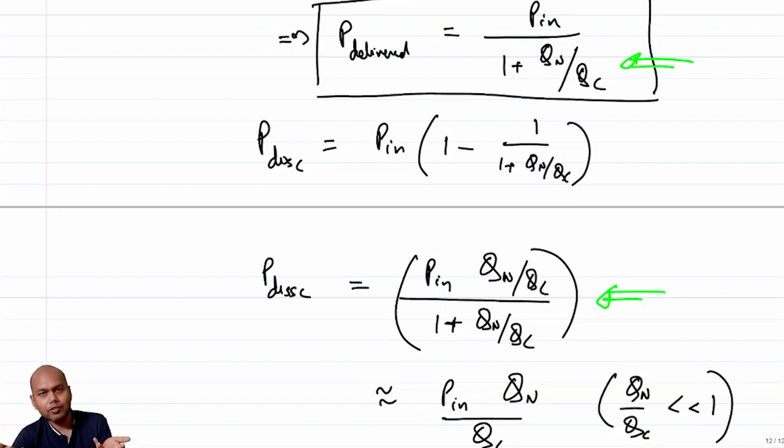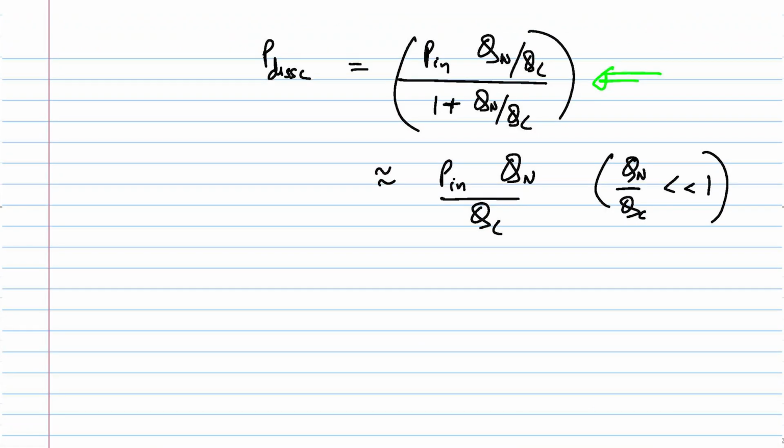Now, if you have a large Q of the network and you have losses in the components, then naturally this points to the fact that you are going to have a lot of losses. Granted, you might have some impedance transformation, but the amount of loss that you are going to have in the matching network in the process of getting that impedance transformation will make the matching network essentially useless, right? So in the next lecture we'll talk about a framework briefly, not in a great amount of detail, as to how to dissociate these two aspects, right? Okay, so let's stop.